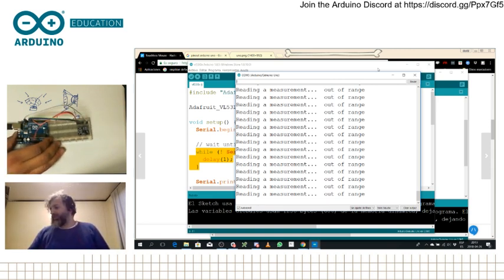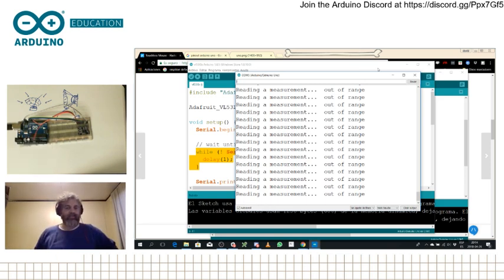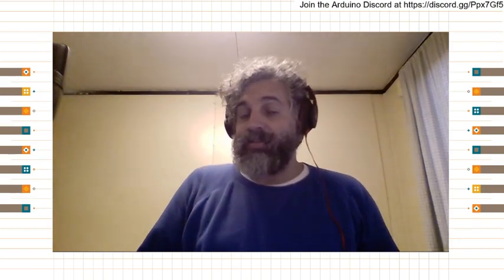And so we've seen different sensors. This one was requested by you guys since a while ago. I'm really happy I could find it in the lab and we could bring it to you so you could see it. We've seen what could be a very good pedagogical way of teaching students about how to use sensors. You could start by detecting presence by casting a shadow, and that's what you do with the LDR. It's super inexpensive, it works out of the box. The only problem is you need to have light in the room so you can detect the shadow. If it's dark, it doesn't work. If you need to detect distance at a longer distance, like 7 meters or something, ultrasound is your friend. There's different types of ultrasounds that can cover all of that distance.